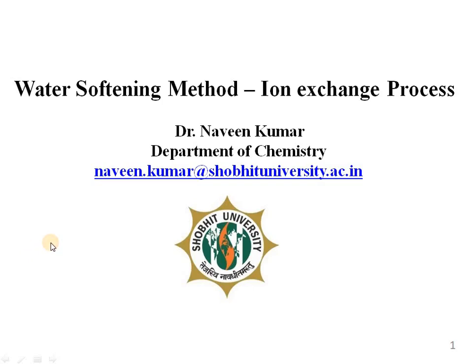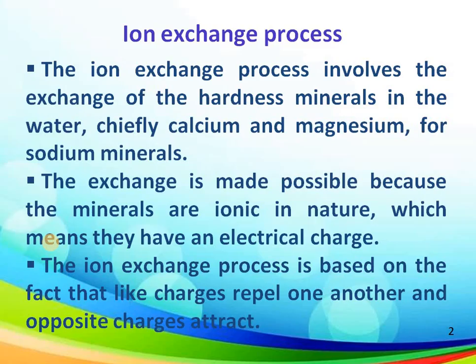Hello students, today we will discuss the ion exchanger process. In addition to the zeolite process, the ion exchange method is one of the most important water softening processes. Basically, in the ion exchange process, we remove the hardness present in the water by using resins.